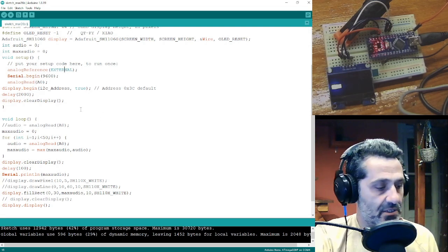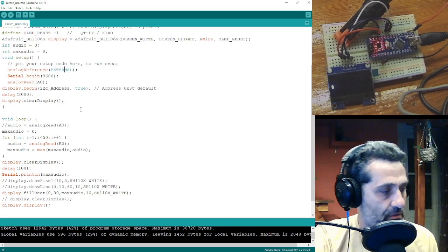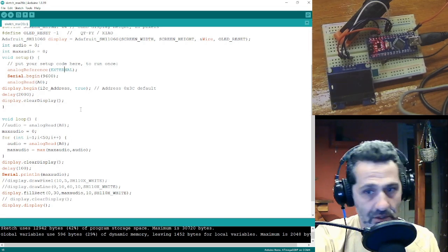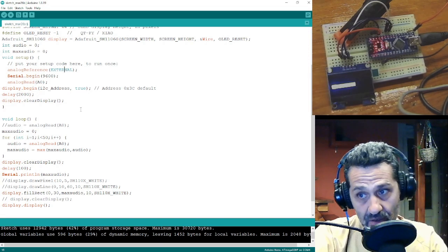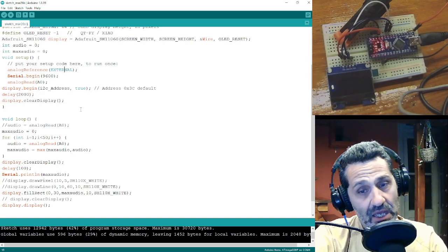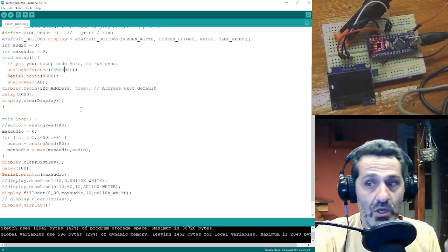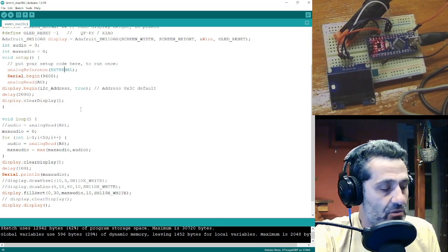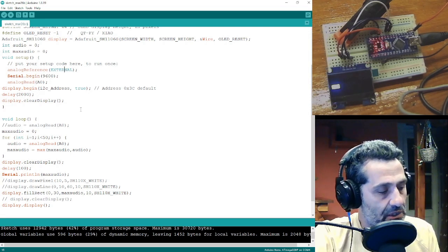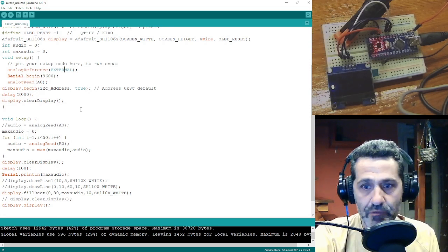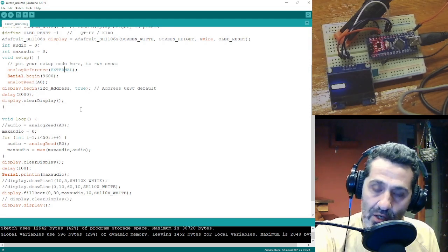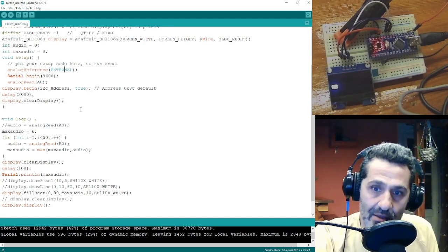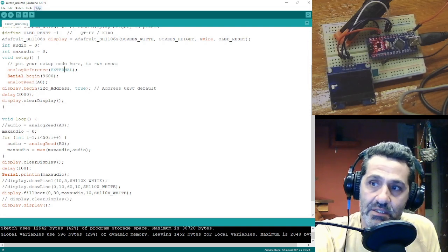So you can just take a wire from this 3.3 volts output pin and hook it on the AREF pin. When you do this, the Arduino will read voltages up to 3.3 volts, which is less than 5 volts, and this will increase the resolution of our readings.